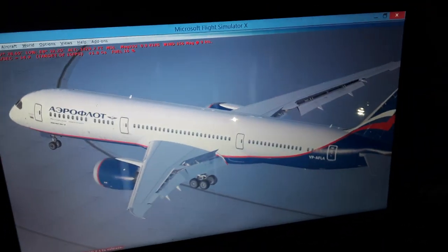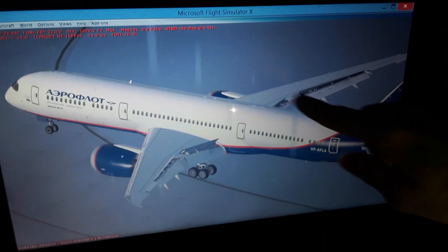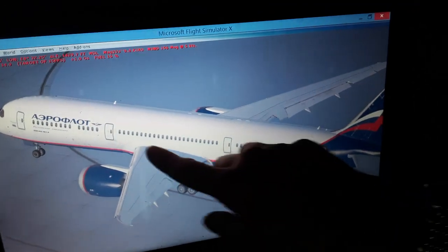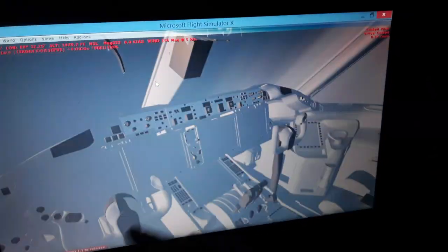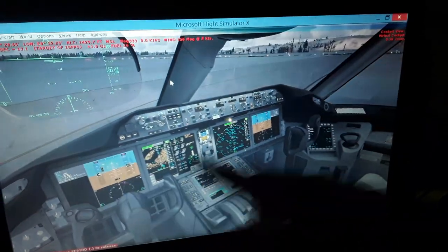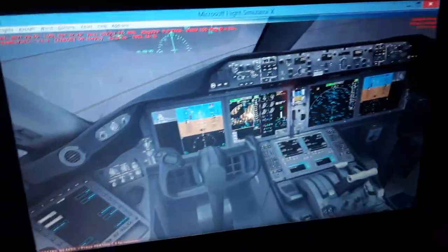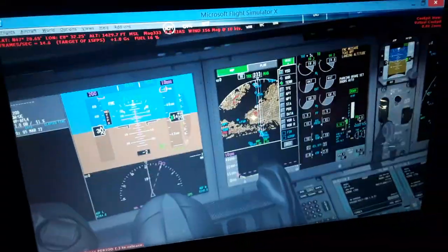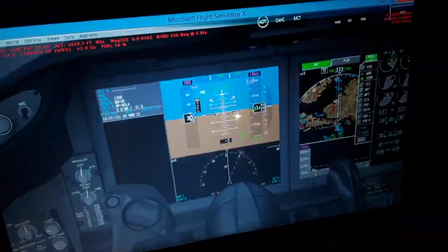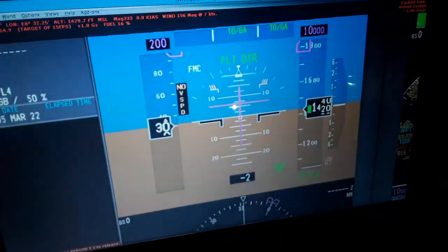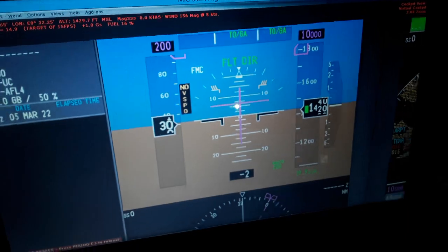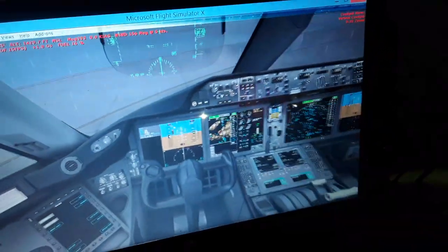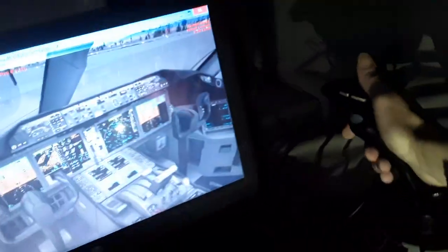Also where the stall begins as we fly, the airflow becomes detached from the top surface of the wings all the way back. So we need to avoid the stall. We need to monitor here the airspeed tape over here, the indicated airspeed. The primary flight display will show us the airspeed, and below the airspeed we need to have the stall speed with yellow and red indication. We need to have a higher airspeed, more thrust when flying, or maintain a pitch attitude down to avoid the stall.